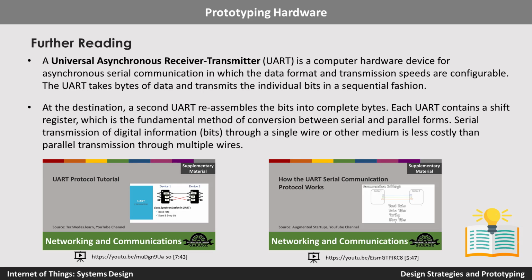Another important term is UART, or universal asynchronous receiver and transmitter. We also call these serial ports. These are computer hardware devices used for asynchronous serial communication, in which data format and transport speeds are configurable. But you need to make sure that you configure both ends, not a single end.